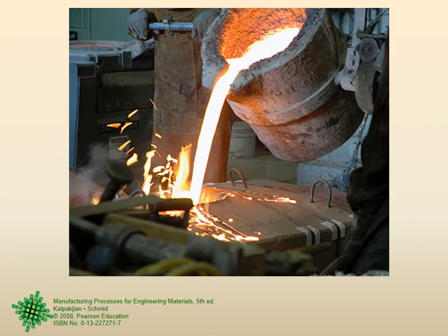I am just showing you a picture, not from the book, but a general picture of the casting process, right? You melt the metal in some furnace, you get this metal into some container, and you have prepared certain molds or dies, and you pour the molten metal into the molds and dies. Once this pouring process is complete, there is the process of cooling and solidification. Once it is solidified, the molds will be opened, and the material will be in the shape that you want it to be in.